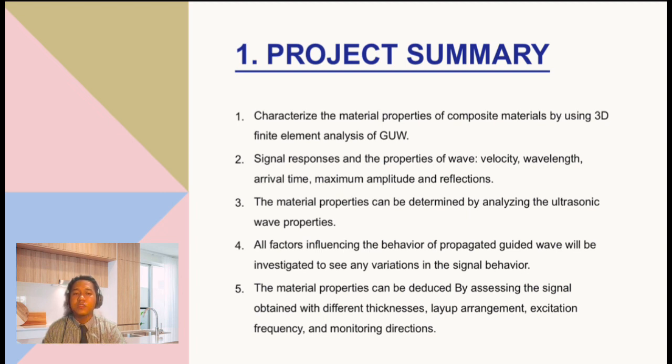This project is carried out to characterize the material properties of a composite material by utilizing 3D finite element analysis of guided ultrasonic wave. Signal responses and the properties of wave such as velocity, wavelength, arrival time, maximum amplitude and reflection are used to obtain the acoustical properties of the composite. By analyzing the ultrasonic wave properties, the material properties can be determined.